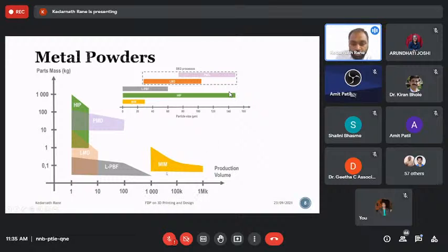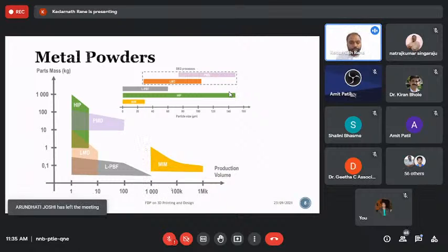When it comes to the use of metal injection molding, you need to consider the cost for post processing as well as the tooling cost, because the tooling is like injection molding, and in plastic injection molding we are going to produce millions of parts. Similar to that, in metal injection molding we consider the process viable and suitable for parts which are required in thousands, all the time.